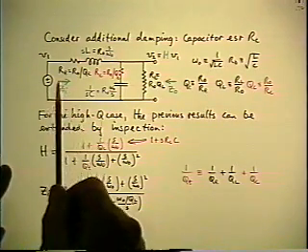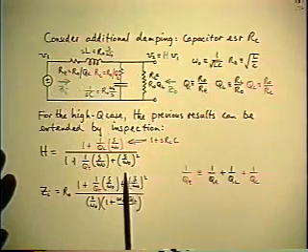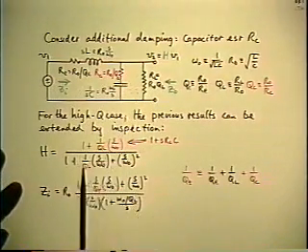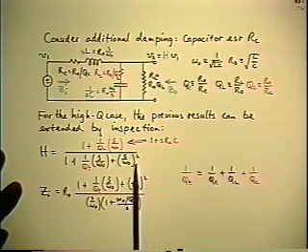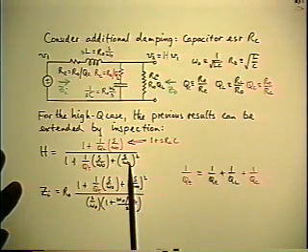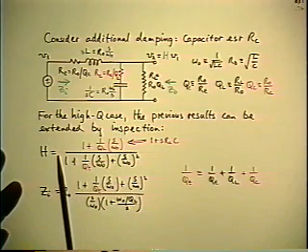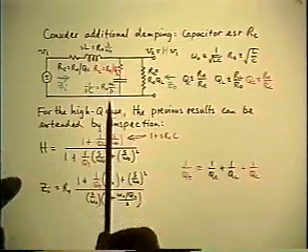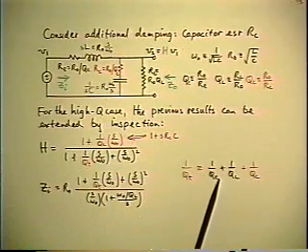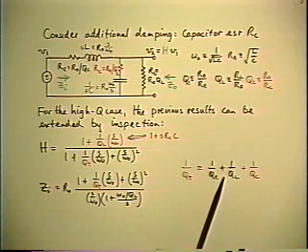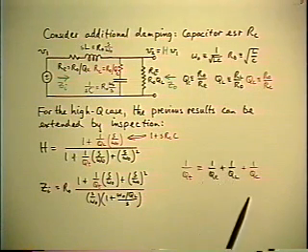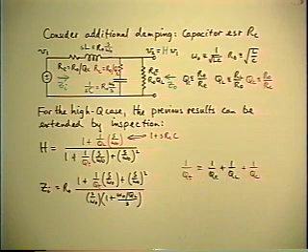So let's do the voltage transfer function first. Assuming no second order effects, we're going to get a quadratic in the denominator with the same corner frequency, omega 0. And there'll be no change of zero frequency asymptote. What's going to be the effect on the Q factor? Well, it's a pretty good guess that it's going to be the triple parallel combination of the three constituent Qs, since that's what happened when we added the second one. Now, of course, that's a guess, but I think it's a pretty good one.